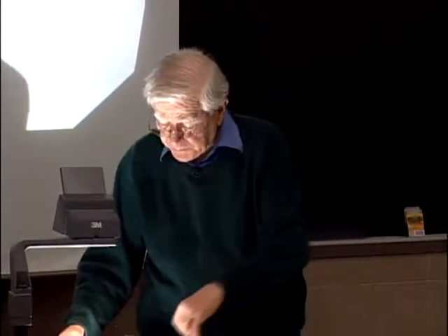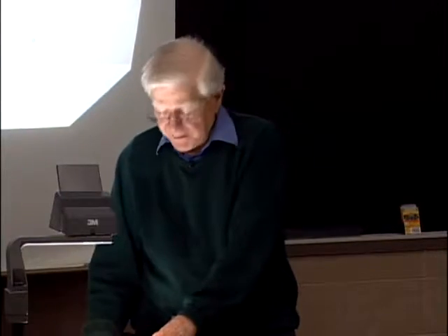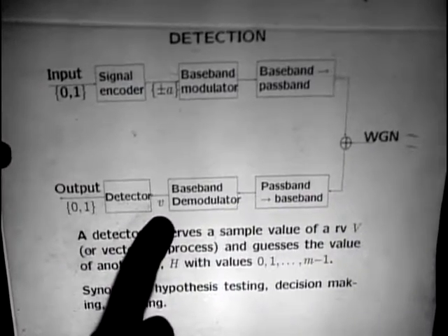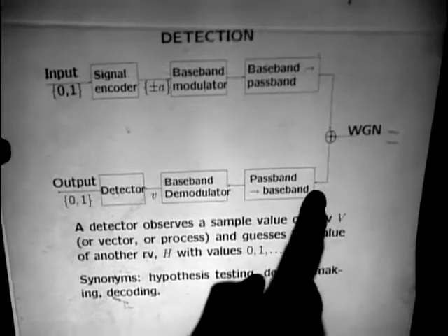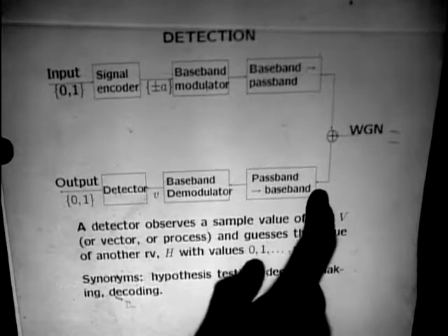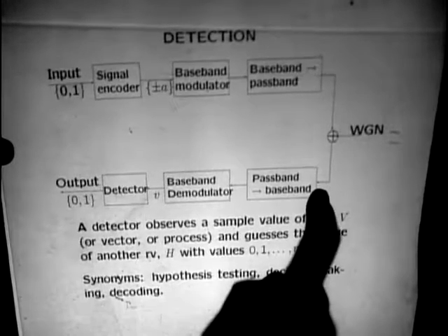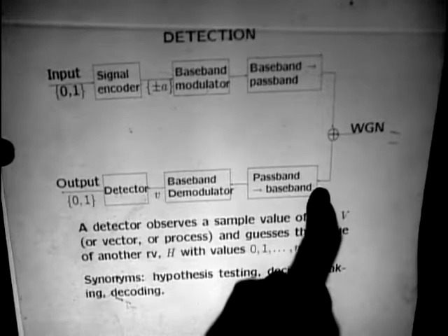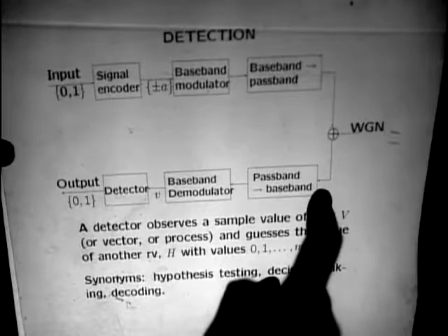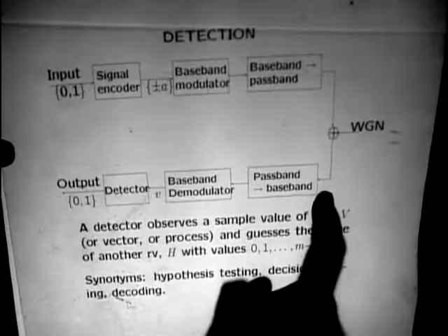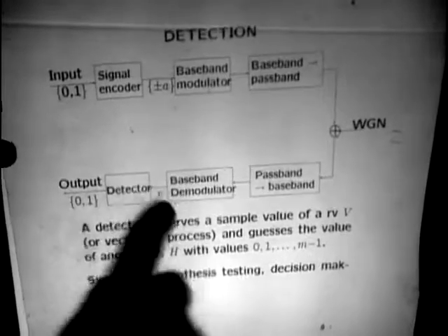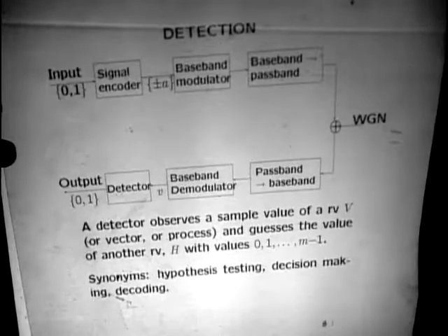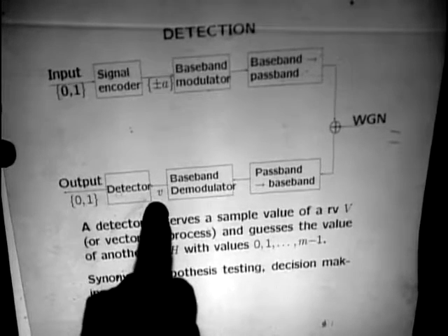What we're going to find out later, when we look at the vector problem, is that this thing here is in fact the likelihood ratio if you make an observation out at this point here. In other words, right at the front end of the receiver, that's where you have all the information you can possibly have. If you calculate likelihood ratios at that point, you're going to go through all this junk right here and wind up with that which is proportional to the likelihood ratio right here.